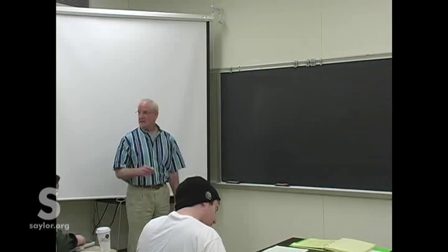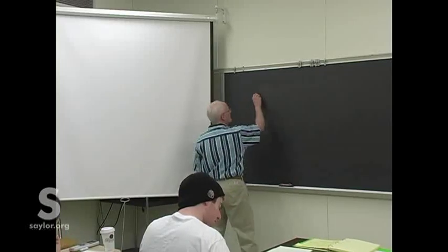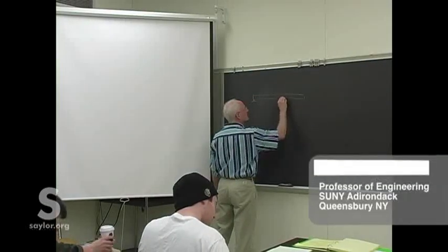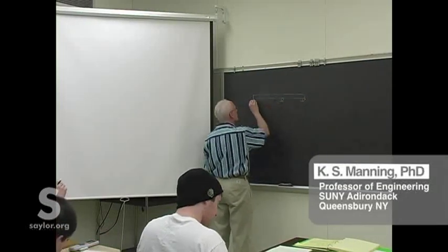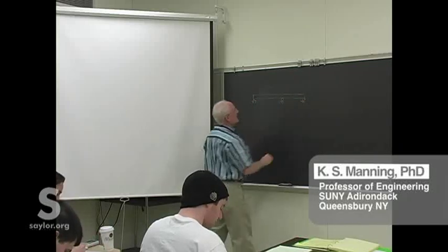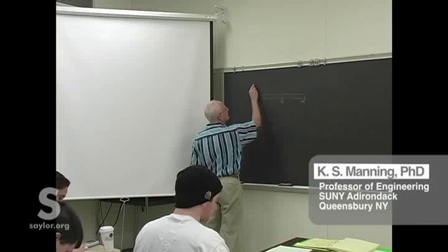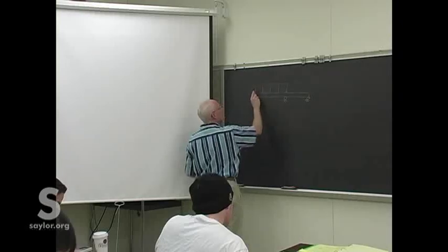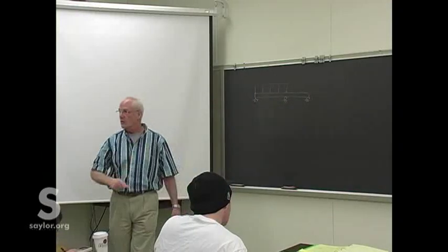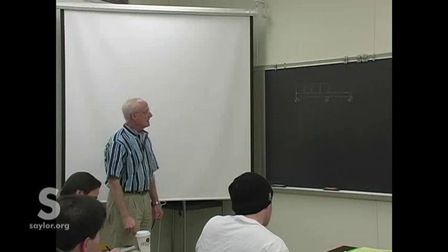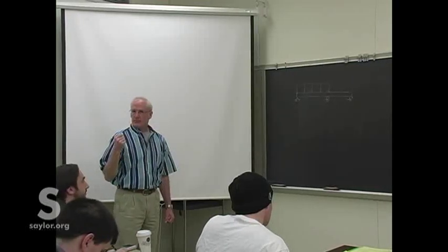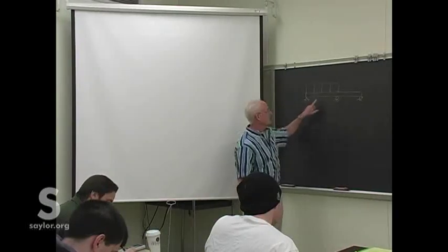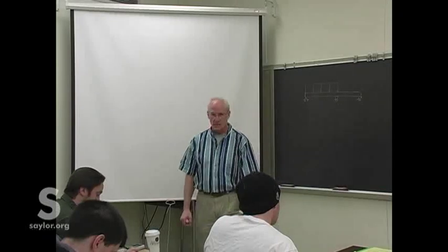We're putting in the last piece we need on these simple beam type problems we've been doing. We've been looking at all kinds of things. You'll recognize this one as an over-constrained beam. There's more supports there than we could solve for. Remember, every time we wanted to do a statically indeterminate beam, which this is, because there are too many supports for the number of equations we have,